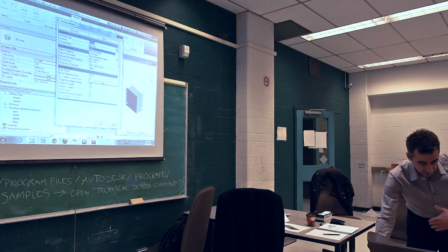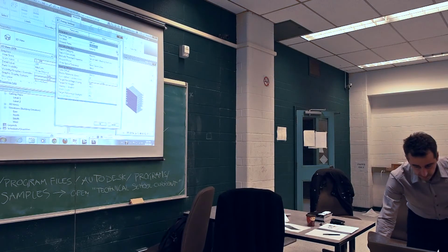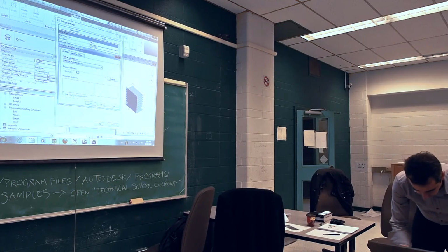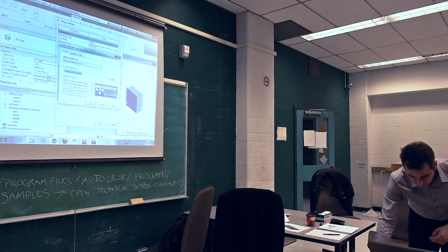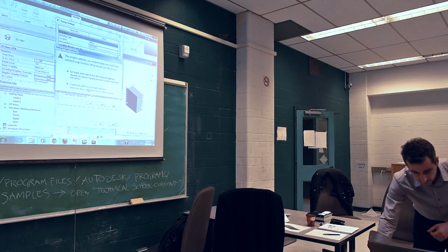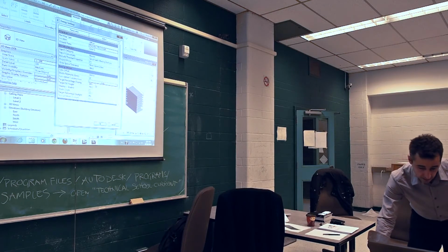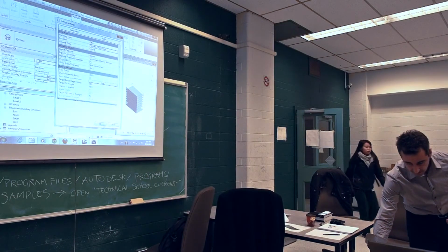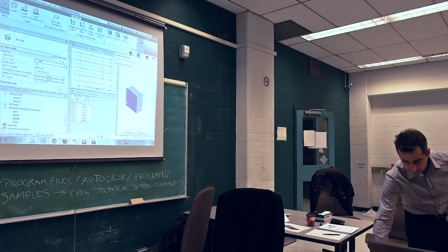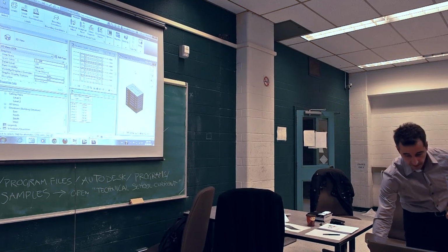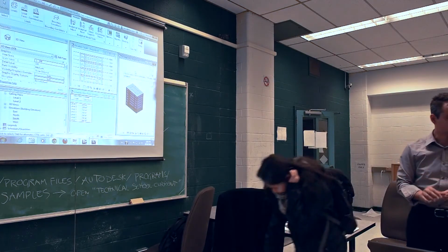Building type office, and I can choose from a number of options. Location, let's just call it, yeah, that's better. And it's going to ask me for what the ground plane is and all that stuff. What I want to do right now for my clients is, let's assume I have a good idea about the footprint and the number of floors and all that stuff. I want to explore the targeted percentage glazing. And the default is 40%. I'll leave it at 40%, and I'll say, you know what, at this point, I'll enable the energy model. So Revit will just create the energy model with 40% glazing.